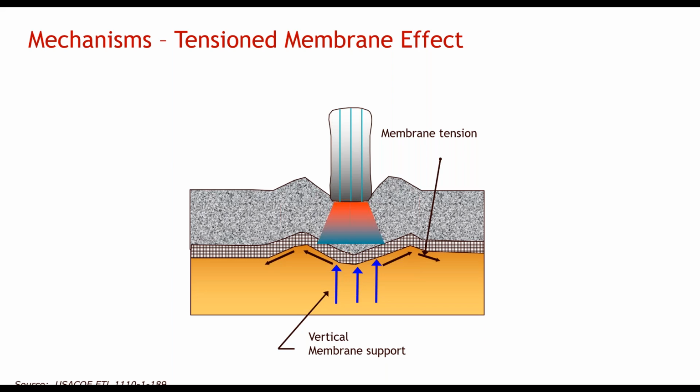Giroux-Norey dealt exclusively with geotextiles and demonstrated the effect seen here very clearly. That is, the tension in the fabric due to rutting creates vertical support. It should be noted especially that the rutting seen in their testing was as much as 11 inches deep. This is the least relevant of the three mechanisms for permanent roads, particularly for geogrids and over strong subgrades.